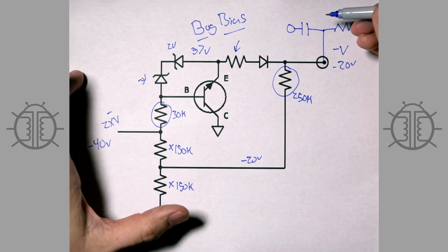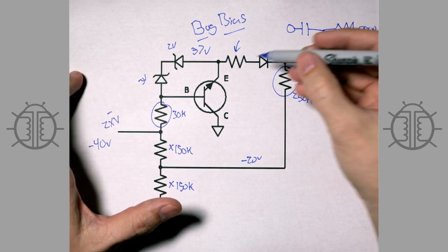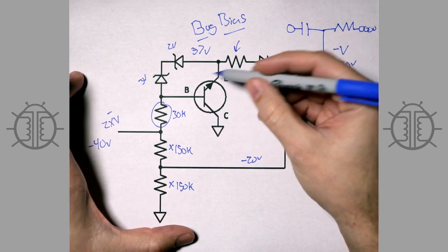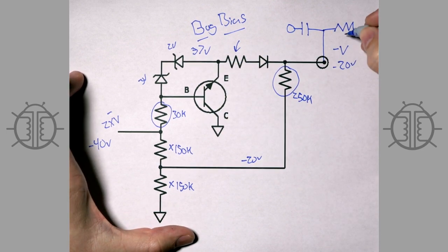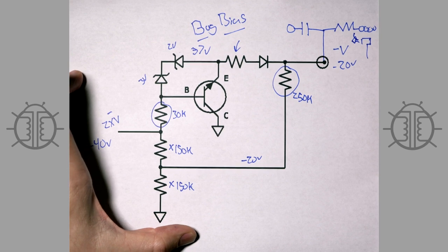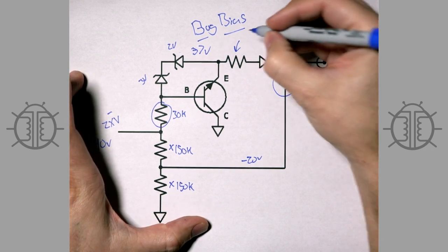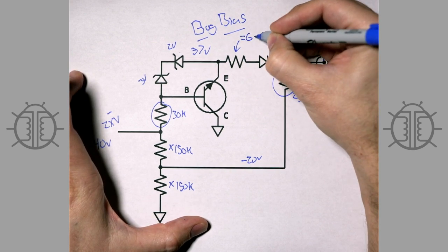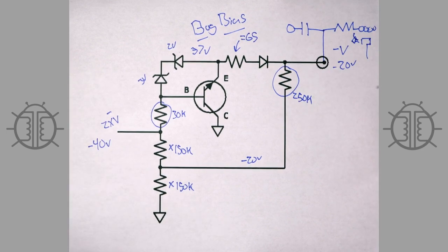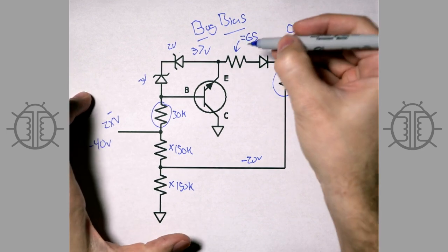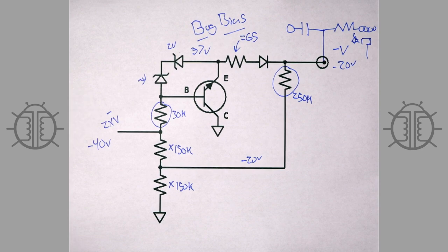So what happens is, when the circuit is engaged, we want it to have a similar resistance to the grid stopper, plus remember our grid to cathode diode. So this is our pretend diode over here. We want it to behave similarly so that it clips symmetrically, so this should be equal to the grid stopper, or possibly a little larger. And it can be adjusted to make the clipping symmetrical.